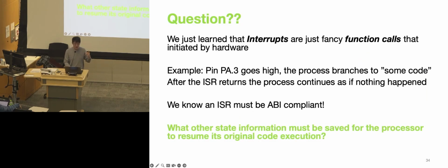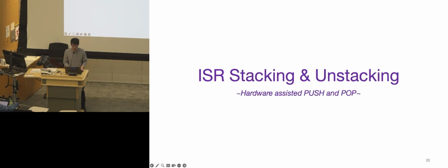So those are the things we will need to store: R0 to R3, the link register, the program counter, the program status register. One more special register, R12, is also going to be stored. Actually, this register is usually used for intermediate calculations within any of the function calls. We will also store that just in case. But I think you get basically all the stuff on this one.